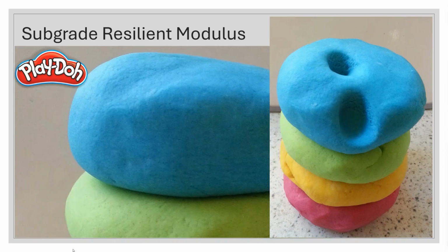It can do a lot more damage. So you see some of that shoving, a lot of the bumpiness, maybe the washboarding, and that's because of the different time that it has to apply the load and how that material responds. So we can see that in asphalt layers, we can see it somewhat in base layers, we see it definitely in subgrade layers and how it responds as a part of that whole pavement unit.